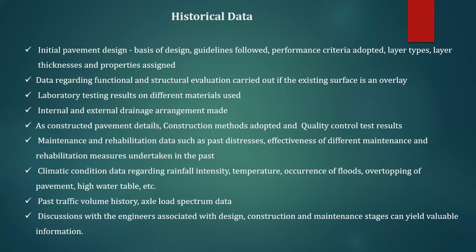Without understanding the pavement condition, the pavement layers, their strengths and the failures, you have to thoroughly understand what is the reason for the failure. For such failures like rutting and potholes, there is no need of a falling weight deflectometer. Falling weight deflectometer analysis for overlay estimation is for when the pavement has some structural failures. So historical data collection is very important: a thorough historical data of the existing bituminous concrete pavement for every kilometer of the pavement you are visiting at the site, you have to take. That is very important.